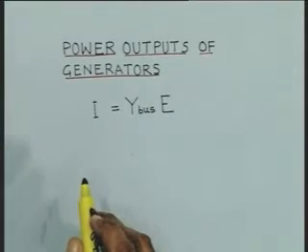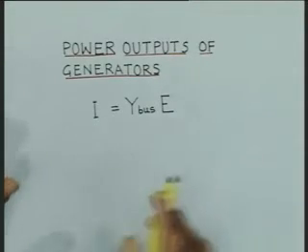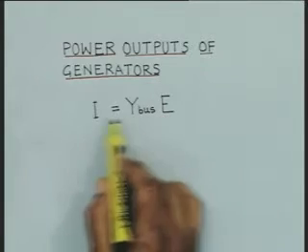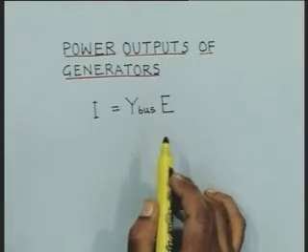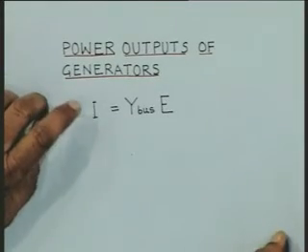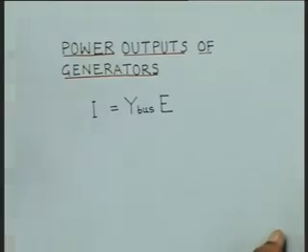Using this we will be in a position to obtain the equations for electrical power output from all the machines, because we know that to analyze transient stability we need the expressions for electrical power output from the generators. Therefore, using this model, which has only the n nodes where the internal voltages of the generators are connected, and this exercise is an important exercise for which I have already explained the methodology.